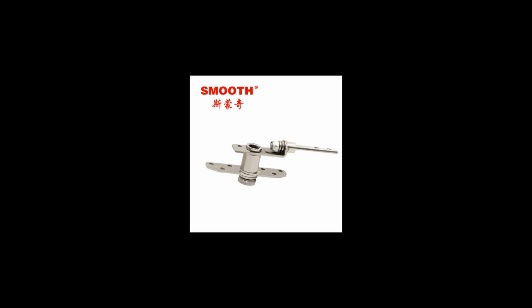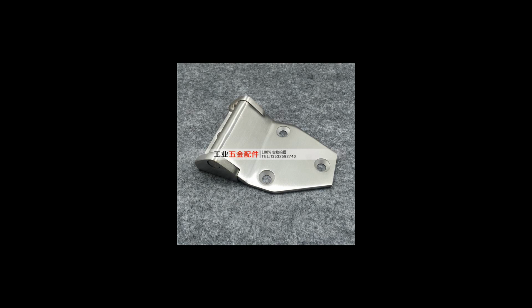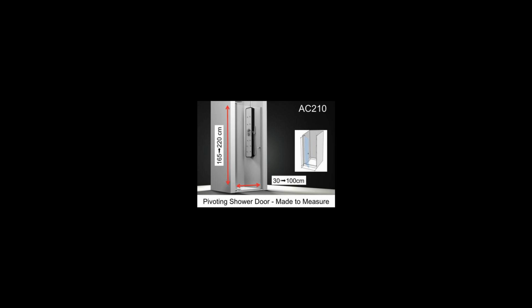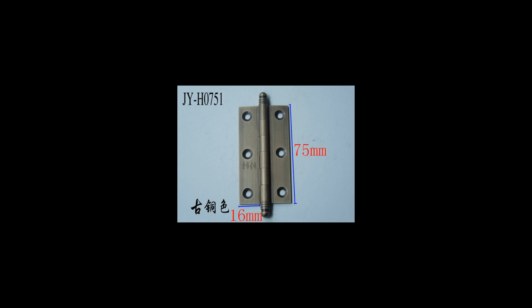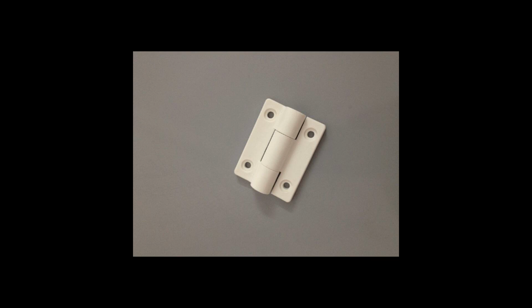Concealed hinges, used for furniture doors, with or without self-closing feature, and with or without damping systems. They are made of two parts. One part is the hinge cup and the arm. The other part is the mounting plate, also called cup hinge, or Euro hinge, as they were developed in Europe and use metric installation standards. Most such concealed hinges offer the advantage of full in-situ adjustability for standoff distance from the cabinet face, as well as pitch and roll by means of two screws on each hinge.